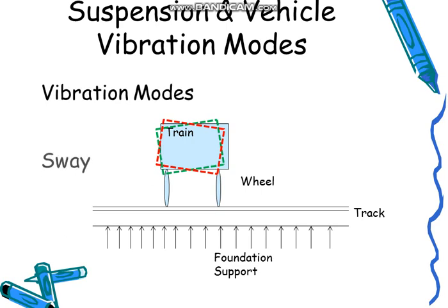The next mode of vibration is the sway. Sway is the vibration mode where the vehicle will vibrate in a pendulum movement along its z-axis. It's like it is pivoted at the center, and the lower edges will be moving back and forth. If it looks like it is hinged on the upper part, then it is upper sway, and if it looks like the bottom part is fixed and the upper part is moving back and forth in this left and right direction, then it is lower sway. So this is the kind of vibration which we call sway.